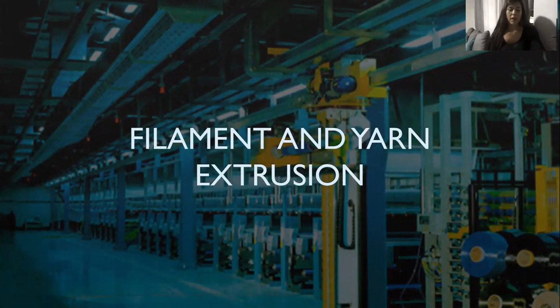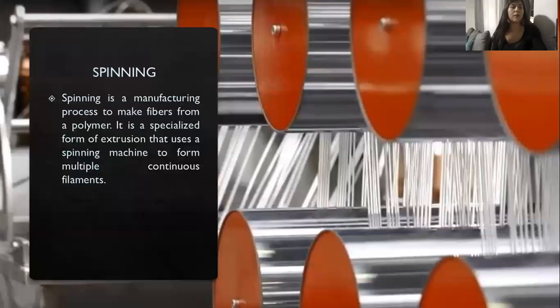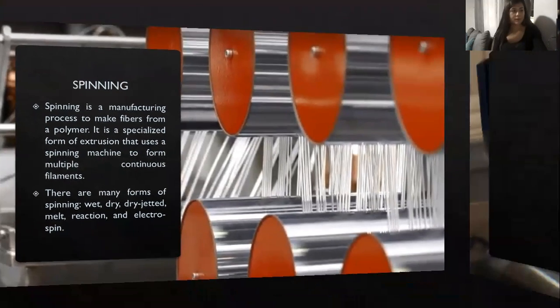Now let's talk about filament and yarn extrusion. We will start with the spinning process. Spinning is a manufacturing process to make fiber from a polymer. It is a specialized form of extrusion that uses a spinning machine to form multiple continuous filaments. There are many forms of spinning: wet, dry, melt, gel, reaction, and electrospinning.